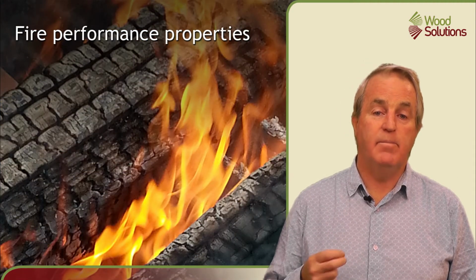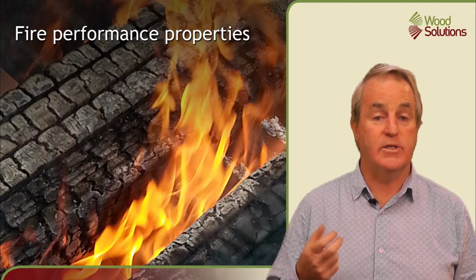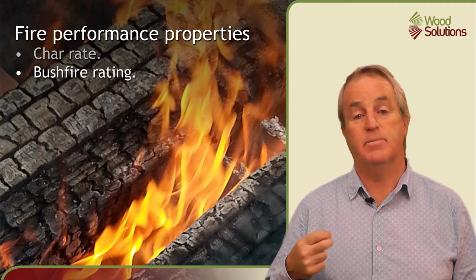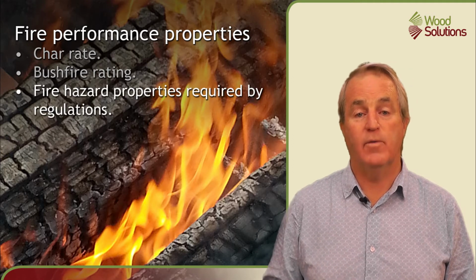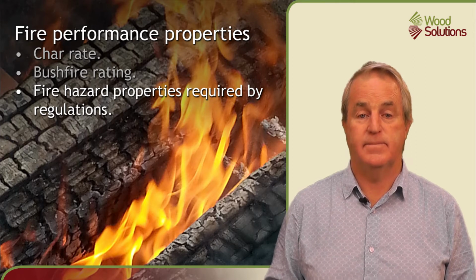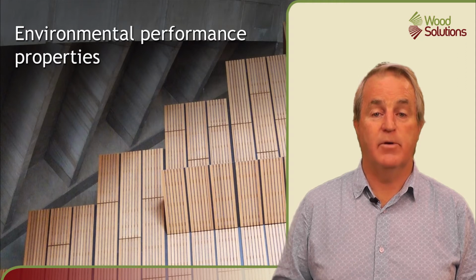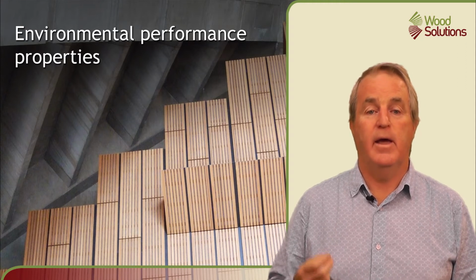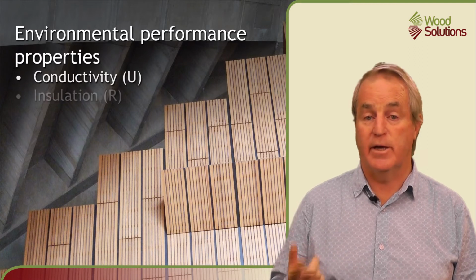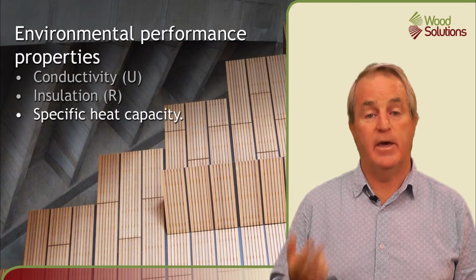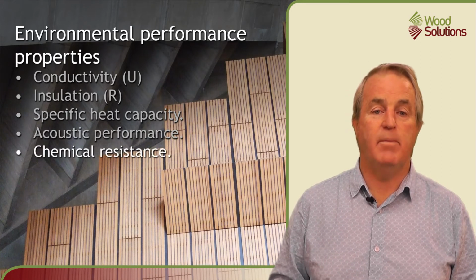Fire performance is important for many applications, and the relevant wood properties are its char rate, its rating when exposed to bushfire, and a whole range of other fire hazard properties required by building regulations. Timber's performance in moderating or controlling aspects of the built environment are also important, and properties that influence this area include the wood's conductivity and insulation properties, its specific heat capacity, its acoustic performance, and its resistance to impact from